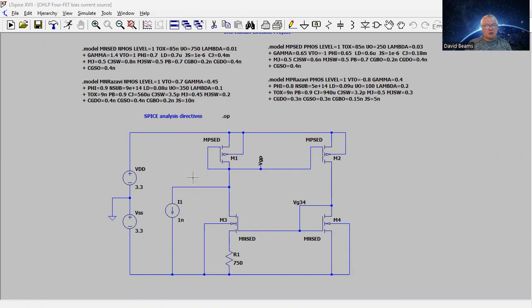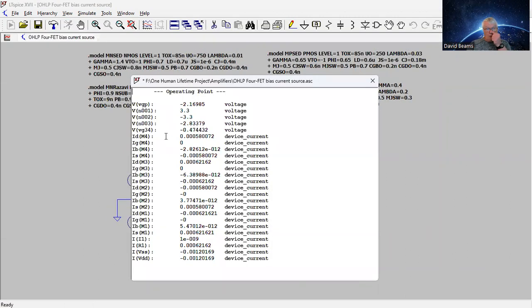One difference between this circuit and the spreadsheet one that is the basis of the spreadsheet, is that I have here this 1 nanoampere source that I've added to make certain that the circuit cannot find a solution at a DC, at quiescent, a DC current of 0. It forces the only solution that this circuit can find to be an active one, not 0 current. Let's run it here, and okay, there we go. It has run, and we can see that, let's pull this out of the way.